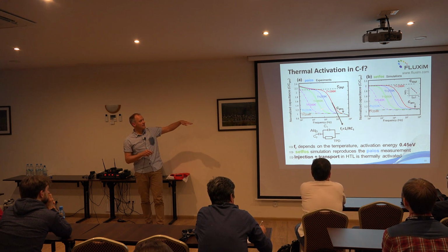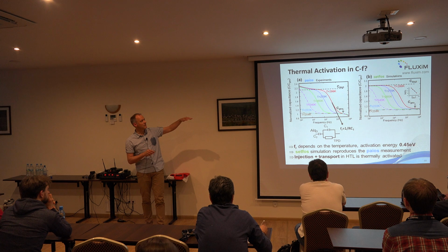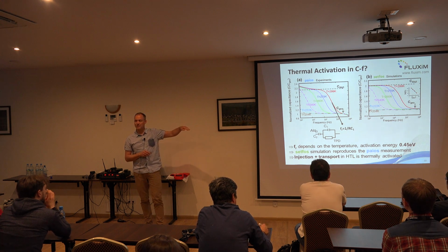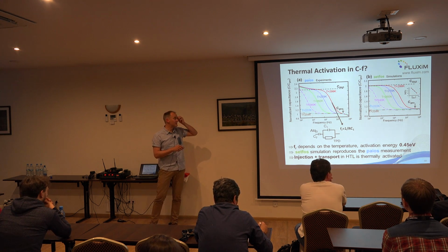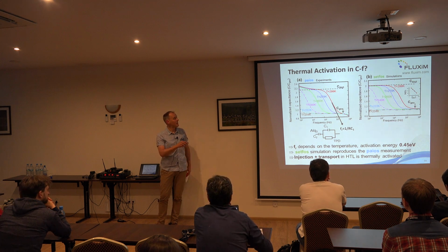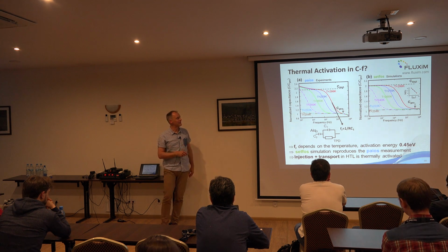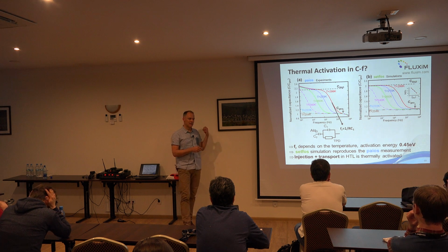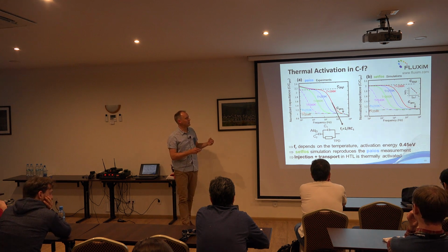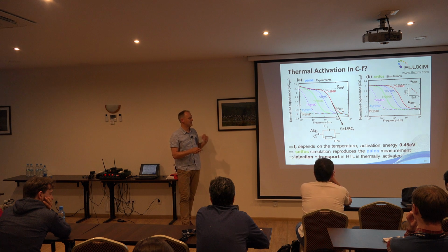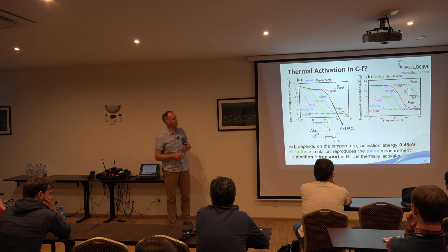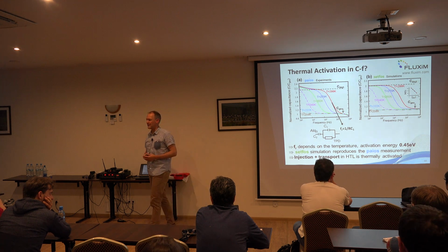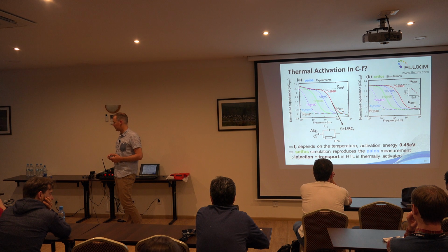we see that the geometrical capacitance value and the second plateau of Alq capacitance is again connected to this hole penetration. If the capacitance is at this level, we have already holes penetrated, and as expected, this will depend on the temperature. At low temperature, we can no longer inject easily the holes into the HTL, but at high temperature we can. So we can even study thermal activation of hole injection into the HTL.